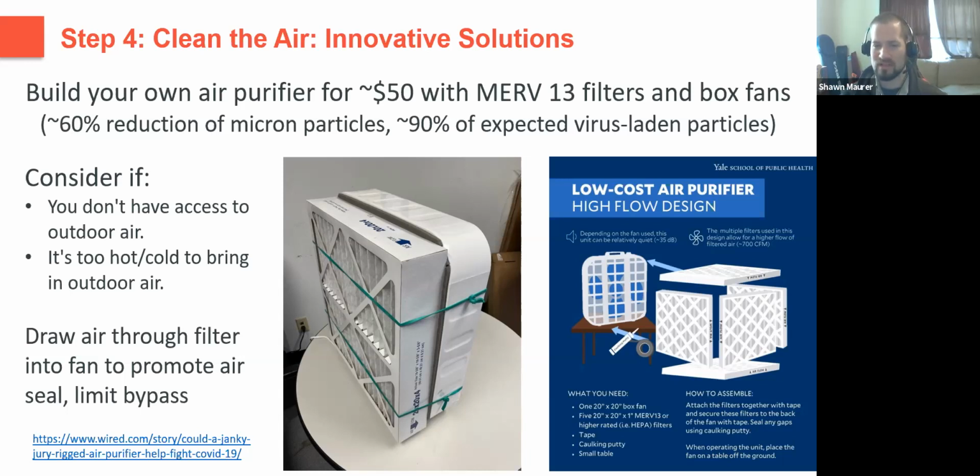It's also important, again, as we noted earlier with the window units, that you don't want to have these pointed directly at occupants. You want them directed towards aisleways between desks, maybe blowing towards a wall or something where the airflow can then diffuse along the wall, and therefore it reduces that airflow velocity that can carry particulates farther away from individuals.